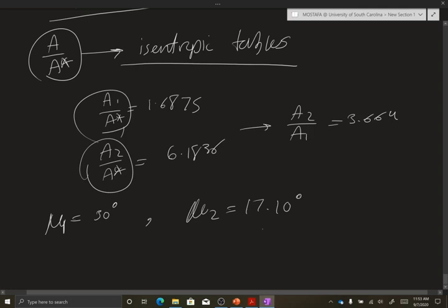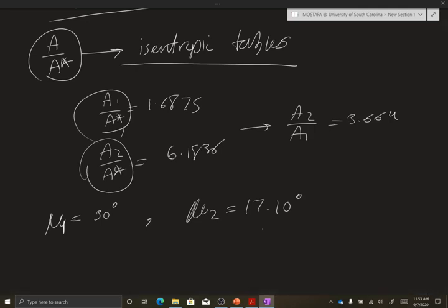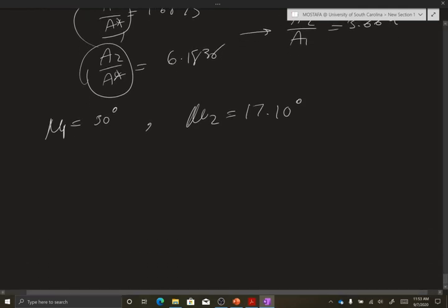So we have the Mach angles, which are the angles the waves make with the wall, right? So your delta, that's the angle between the first Mach angle and the last Mach angle, is going to be theta plus the difference between the two Mach angles, right?